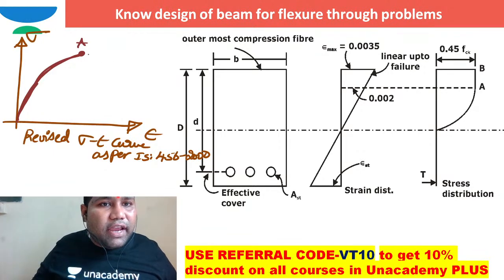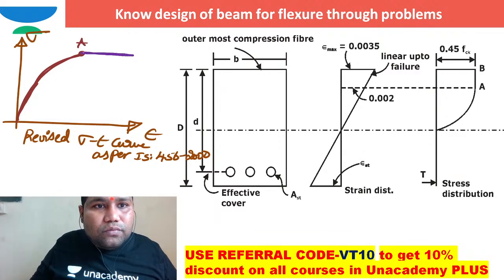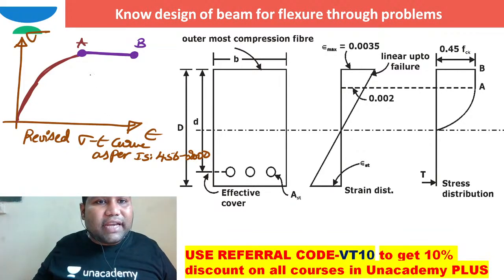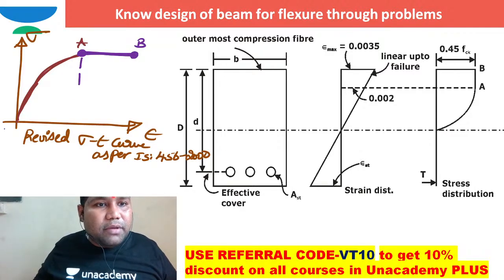So instead of treating it as a strain hardening zone, the code has taken A to B as a flat zone, because in the original stress strain curve the increment in strength is very less. In the crack widening zone, the stress strain curve is made flat. So this is OA and this is AB.